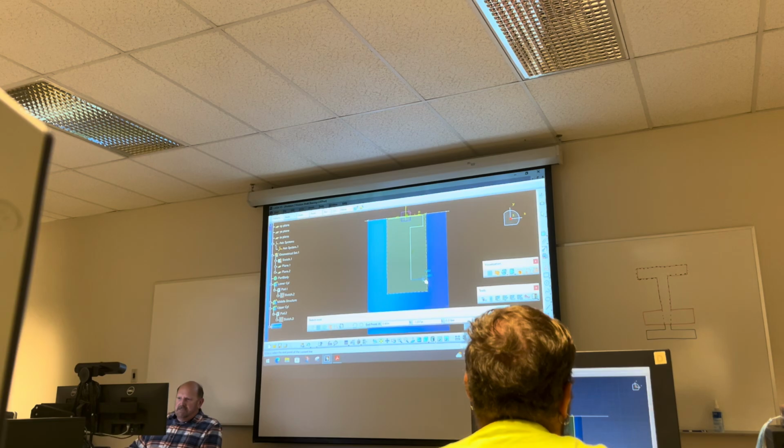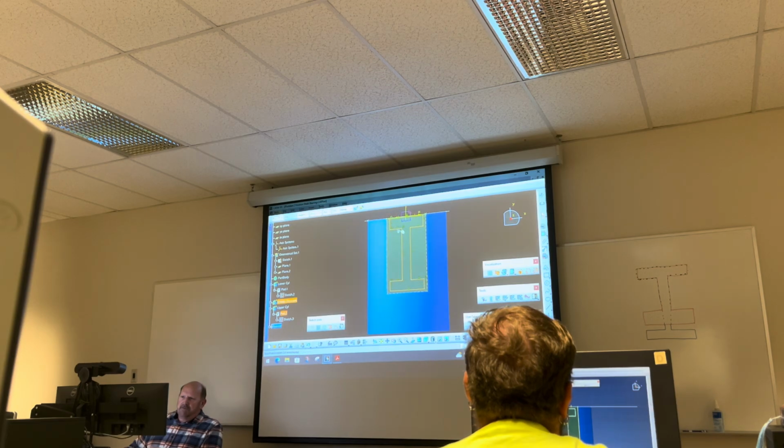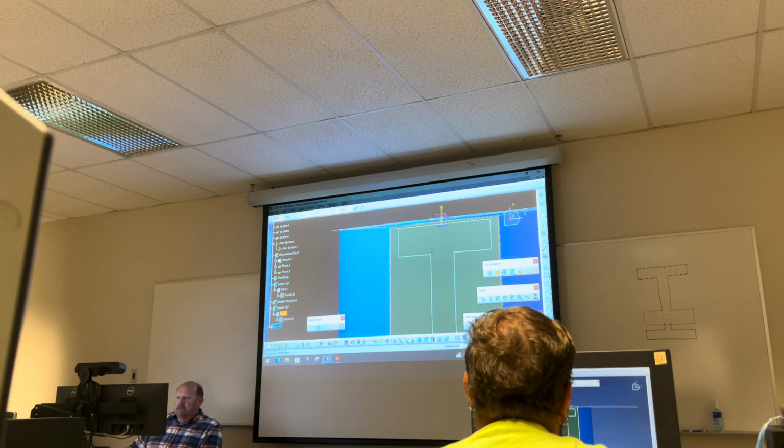And this is a pretty easy sketch. When it wants to line things up from the other elements, make sure that you click where it's gonna line those up. That way you don't have to go back and screw around with trying to make sure that some of these edges aren't looking for the other side of the solid, like this one right here. I'm gonna finish it by going straight up. And I can see that obviously this one's gonna need to be trimmed.